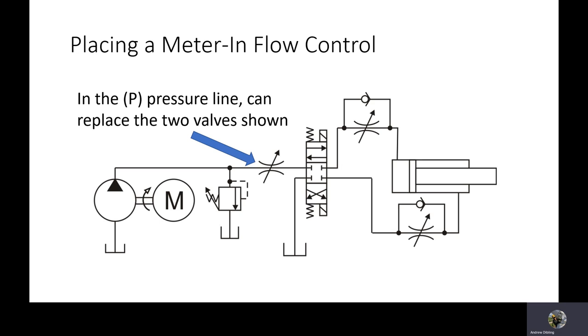So when this is pumping this way, again, fluid will go through here. It won't go through the check valve on the bottom side because it's pumping up against that closed ball. It must go through the restriction and it will retract at a slower speed.